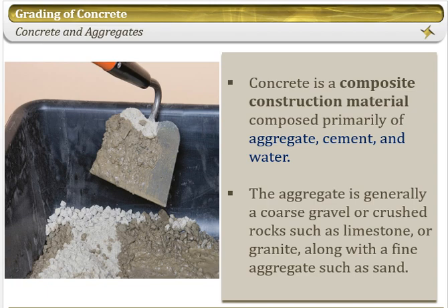Coarse aggregate includes gravel and crushed rocks, such as limestone and granite. These crushed rock particles are also known as coarse aggregate. Actually, the size of the coarse aggregate is more than 4.75 mm when we do the sieve analysis, and 2 mm to 4.75 mm aggregates are also known as sand. Locally, we know the coarse aggregate as gitti or rodi, and fine aggregate is locally known as bajri.